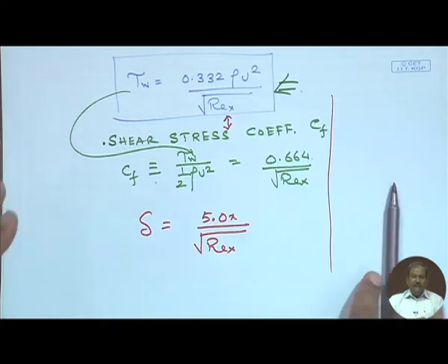So one can see then that through the use of the Navier-Stokes equation, boundary layer approximation, identification of the appropriate boundary conditions, evaluation of a combination variable which combines both y and x into eta through an order of magnitude analysis, and introduction of stream function and a dimensionless stream function, all these complicated steps are necessary to convert the Navier-Stokes equation for two-dimensional flow inside the boundary layer to an ODE.